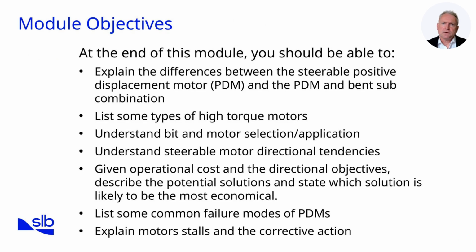At the end of this module, you should be able to achieve several learning outcomes. First, you will be able to explain the differences between a steerable PDM and a PDM used in combination with a bent sub. You will also become familiar with types of high torque motors, an important category for challenging formations where extra power is needed. Another objective is to understand bit and motor selection criteria and how these choices impact drilling performance. We will also address the directional tendencies of steerable motors, helping you predict and manage well path outcomes.